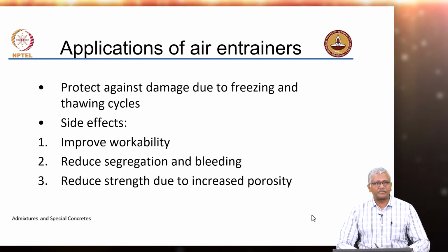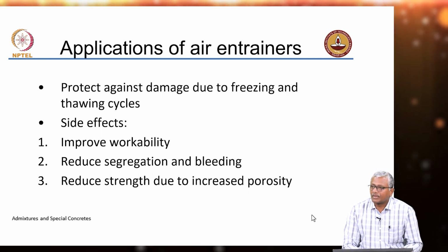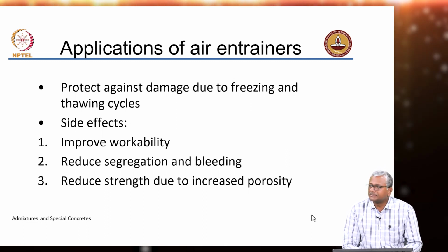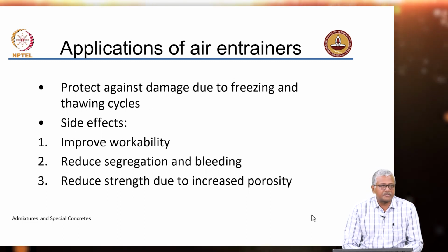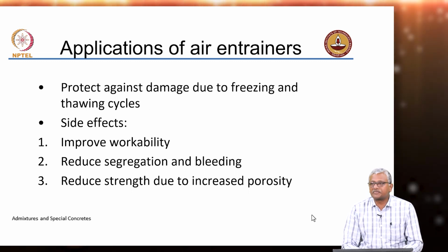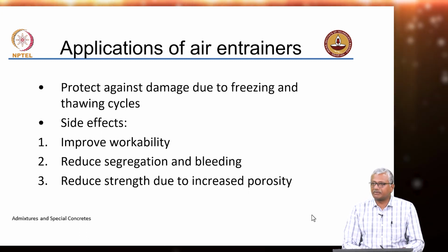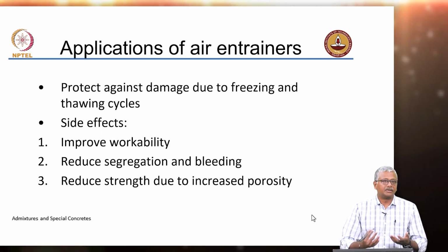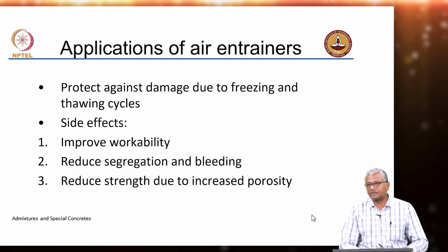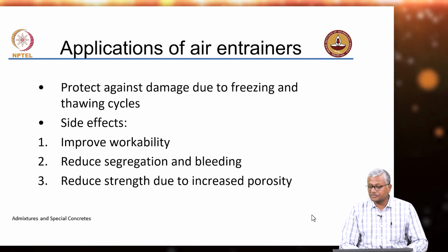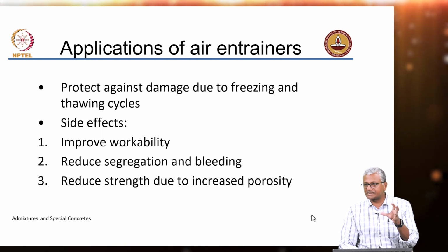Now, what happens upon freezing? Why are we worried about that? Water expands, right? Whatever free water is present in the concrete will expand, because water has this anomalous behavior that it actually does not contract, but it expands upon freezing, and this expansion leads to stresses in the concrete.